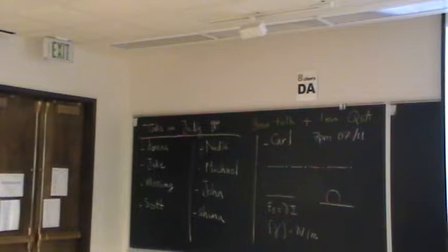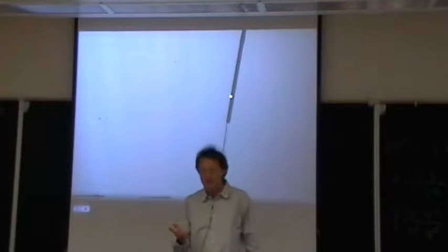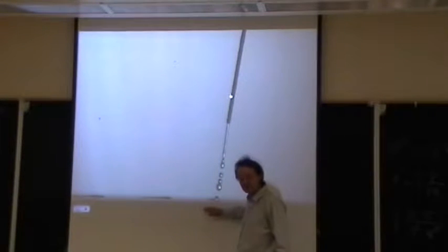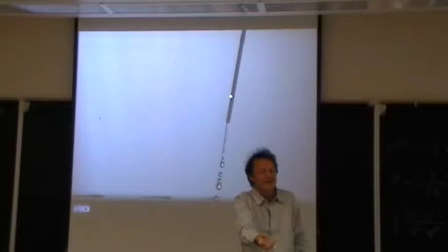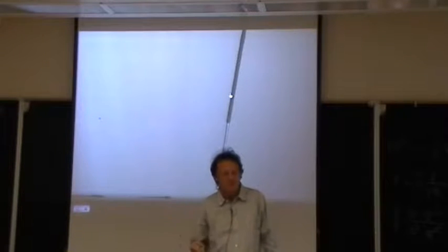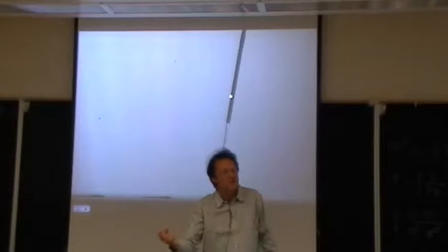But now, if you come with some velocity, so if the velocity of the drop is large, then you do not understand exactly what happened, but the movie is funny because it tells you that there is also a threshold of entrainment, which for a fixed velocity here, which is, I think, if I remember correctly, 15 meters per second, so we are in the high velocity regime, depends now on the velocity of impact. And this has to do with the initial formation of a film, which is enough to sustain the drop. So if you come across this film, you can touch.